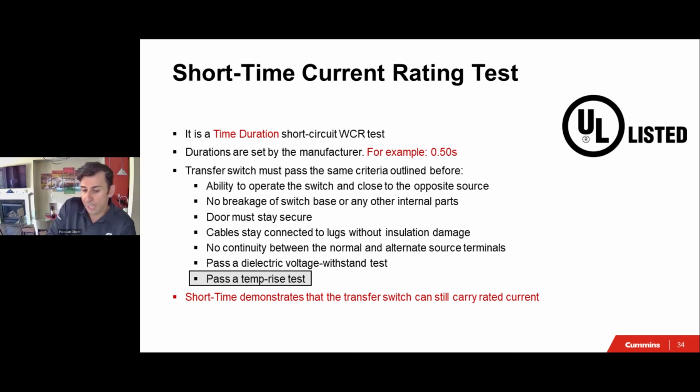That means if you have a short circuit incident, and then you have multiple branches in the circuit, and this ungodly amount of current is going through the transfer switches, through the distribution boards, 85,000 amps, and then we're giving time for the breakers downstream to clear that fault, closer to the fault.